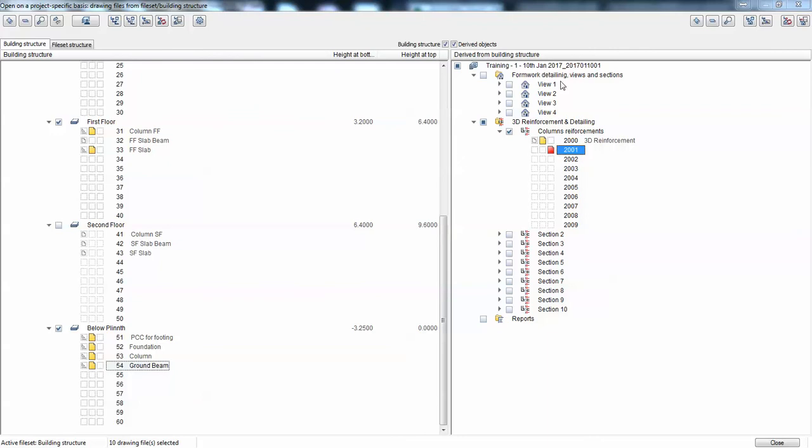Organization of the project: here we'll place the formwork and any detailing regarding the concrete only. And on the sections part, we will do the reinforcement. An important aspect is to keep in files only the 3D reinforcement. So in some files we'll only have the 3D rebar, and on another file we'll have the associative views for detailing.